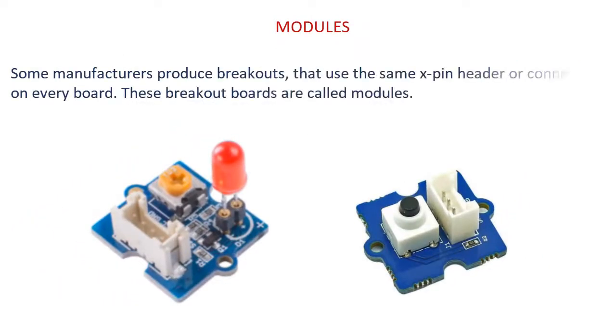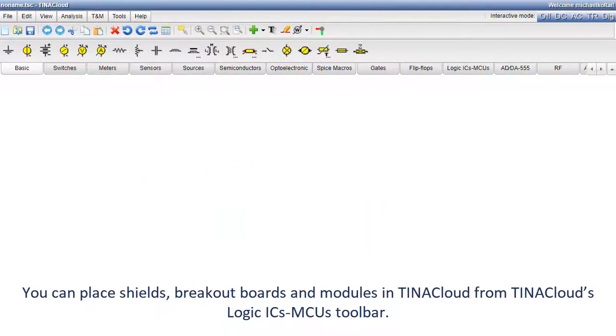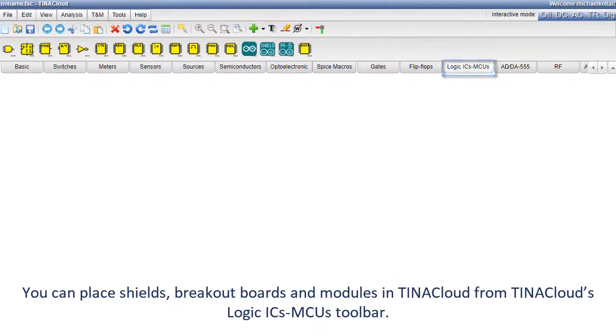Modules. Some manufacturers produce breakouts that use the same X-pin header or connector on every board. These breakout boards are called modules. You can place shields, breakout boards, and modules in TINACloud from TINACloud's Logic ICs MCUs toolbar.